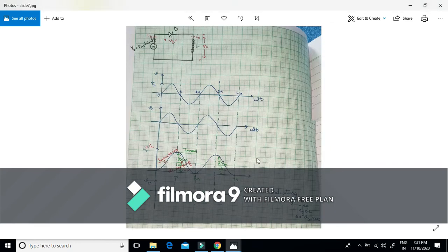Now, the second one is the single phase half wave uncontrolled rectifier. That means again we are using one source voltage, again we are using one diode. But in the previous case that was a purely resistive load, and now we have a purely inductive load. Here also I naught and V naught represent the current and voltage across the load. Again, because it's a series circuit, the source current Is will be equal to I naught.